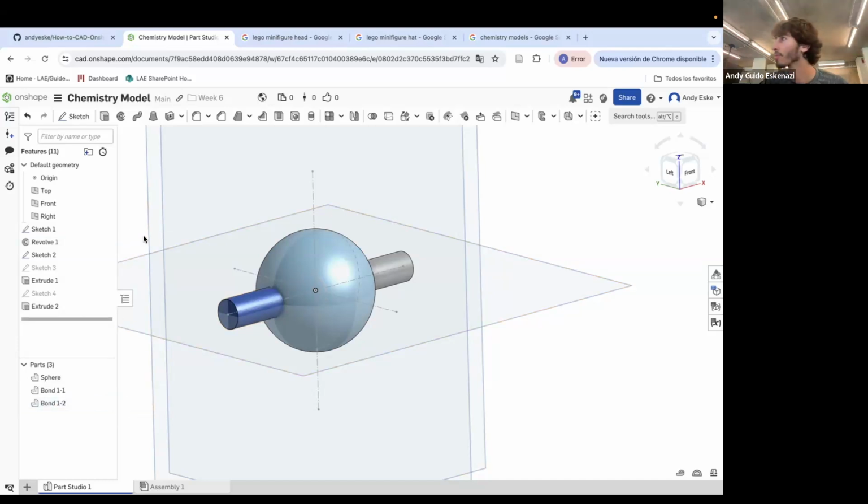To create the cylinders, you had to create a plane and then... well, you could create a plane, or actually, I'll still leave it as a plane. I thought it was just easier to go here to sketch, and you already have the plane there. You start it from the origin. And we give it a 15. Actually, that might be too much. Give it 10. And then extrude new up to vertex.